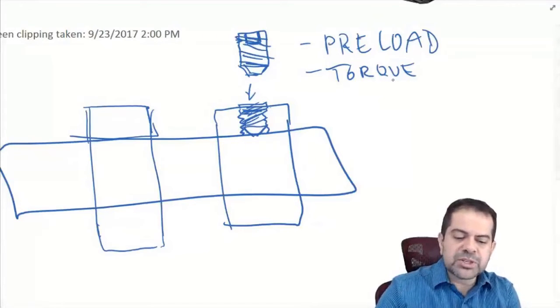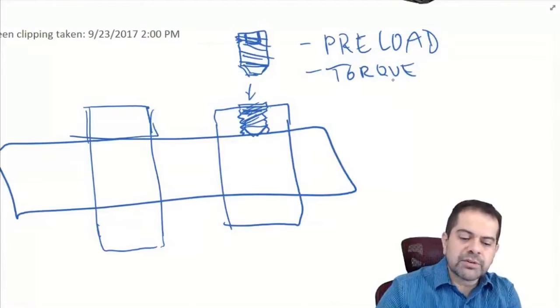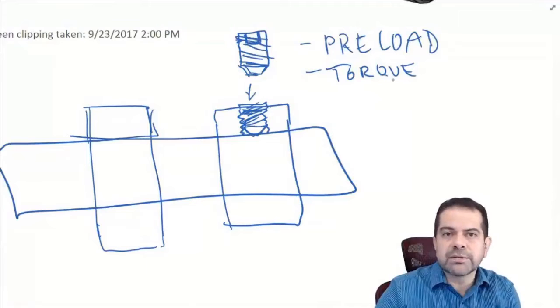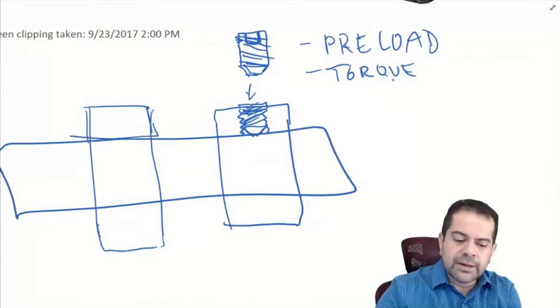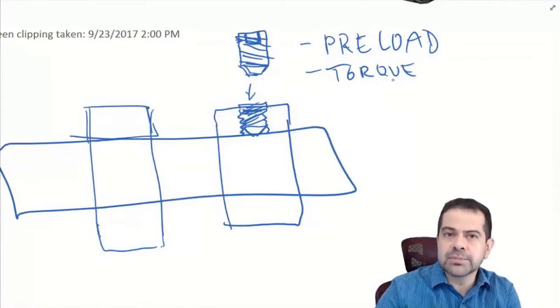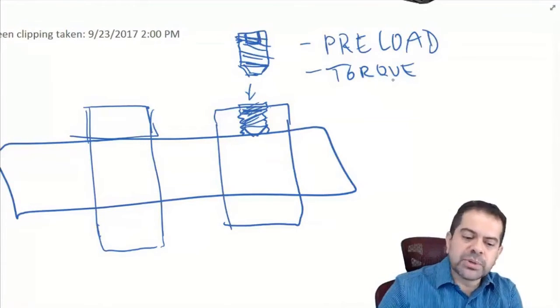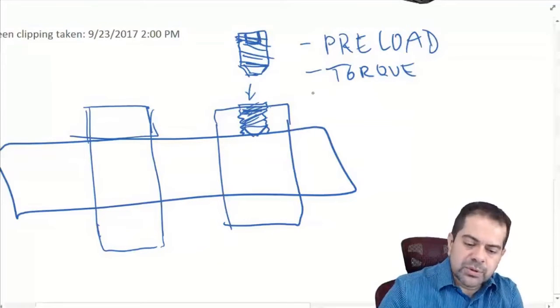So in machines, there can be shock and vibration. Almost no matter what amount of torque you have, even if it's adequate, chances are you're running the risk that it'll loosen and back out. So torque by itself may not be enough. So another method to set them in place,